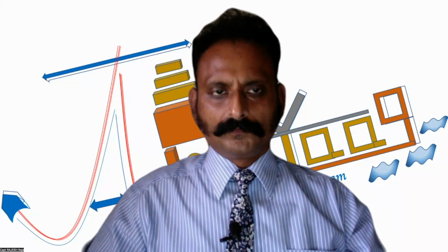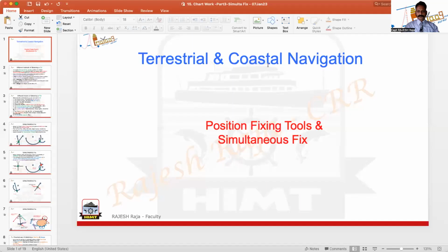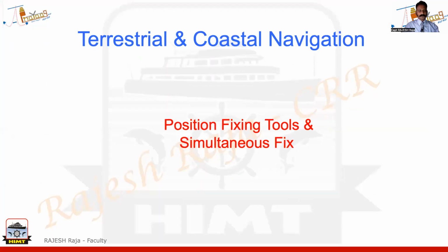As I had mentioned while doing the last video, I was talking about making a small presentation regarding position fixing tools and how you can do a simultaneous fix. Because fix is one of the most important features in your chart work. End of the day, whatever you are doing in navigation, my ultimate aim is always to get my position, which is a fix. So let us look into the different position fixing tools and let us see how we can do various methods of simultaneous fix.